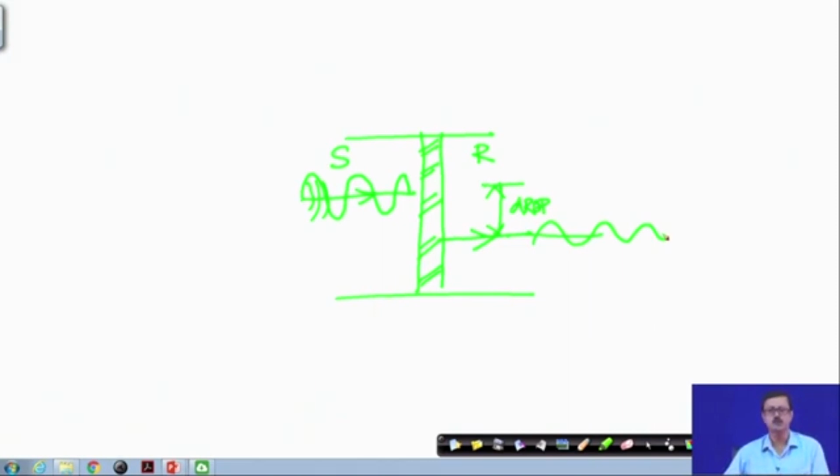And this is the airborne sound transmission. Very similarly, there may be structure borne sound transmission, because maybe this is a concrete slab and there is some machine or some object which creates a vibration and sound, and the sound will travel through this surface itself and propagate and enter into the other receiving room, and this is called structure borne sound transmission.